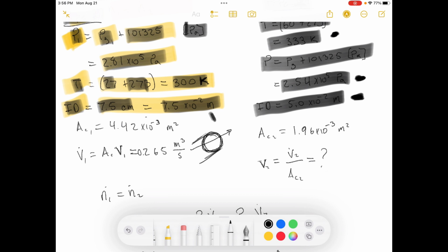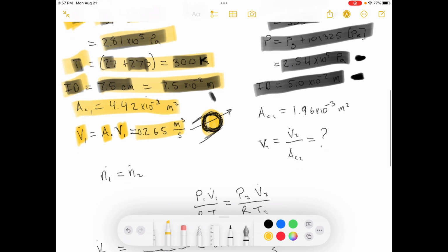If you assume the same velocity across the pipe, like the average velocity they gave us, you can just multiply it by that cross-section, and that gives you the volumetric flow rate. This is a circular pipe, so the cross-sectional area is pi r squared. So, volumetric flow rate is the cross-sectional area times the velocity, and you get that.